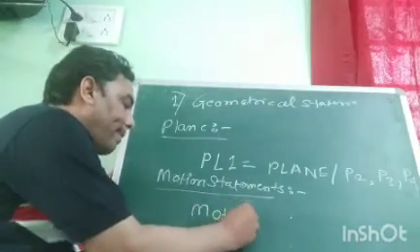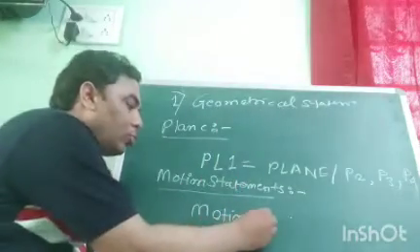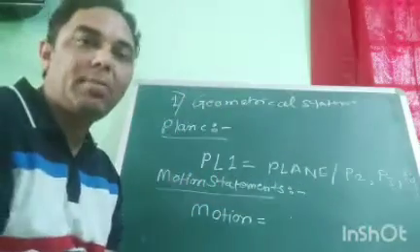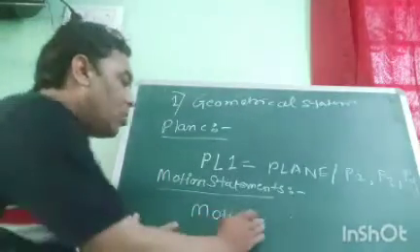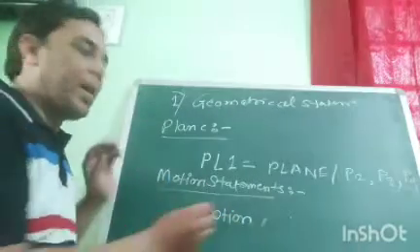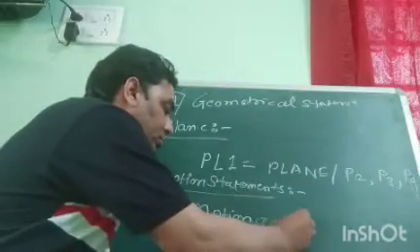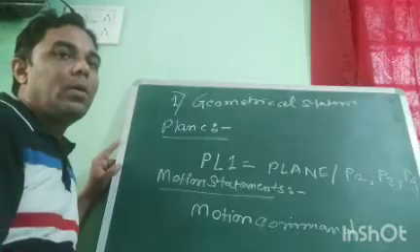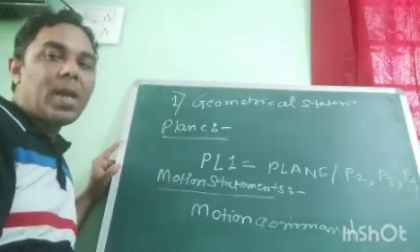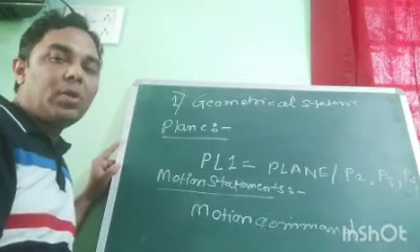The general format for an APT motion statement is the motion command. As we have seen in the geometrical statement, where we write down the symbol first, here we need to write down the motion command, and the descriptive data where we need to perform the motion.